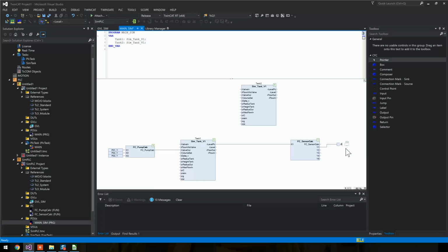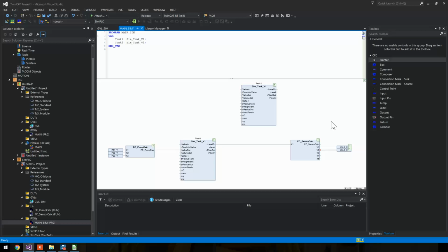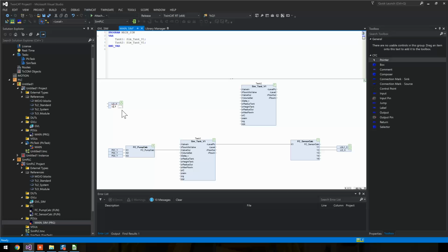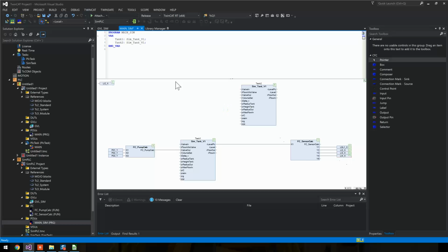The lowest one, level switch low 1, X. If you would like to learn more about why these letters have been chosen, you can look into the ISA 5.1 standard for tags and P&ID. High 5.